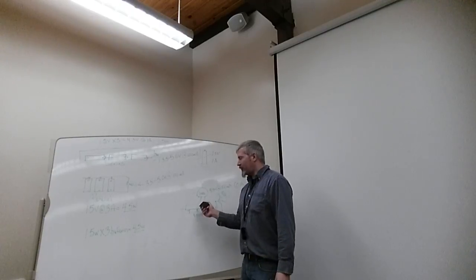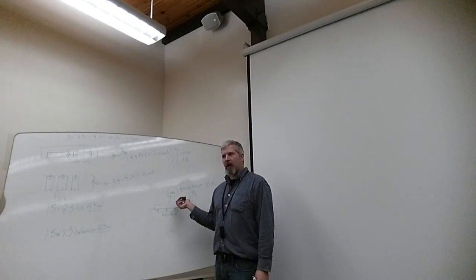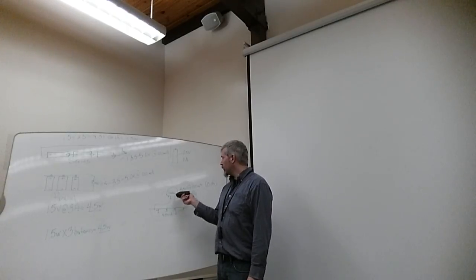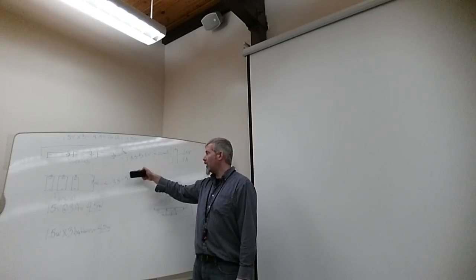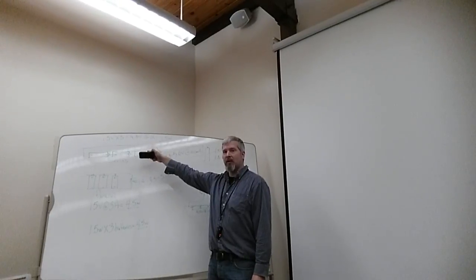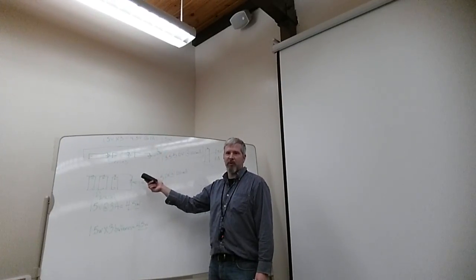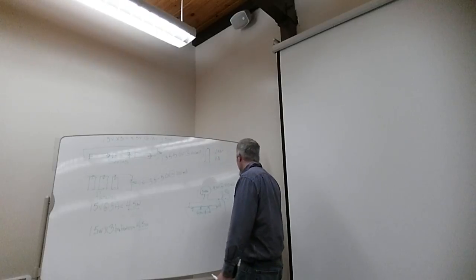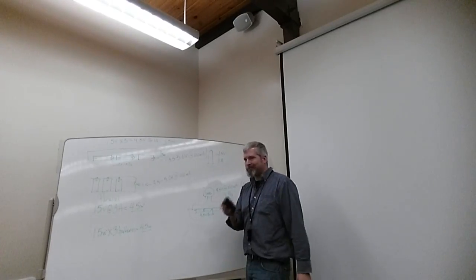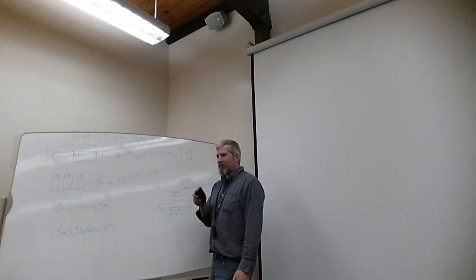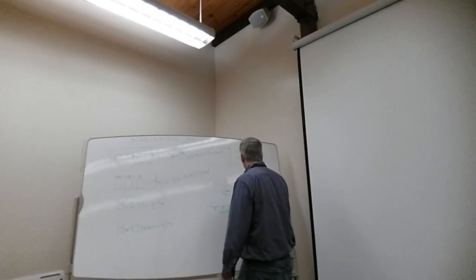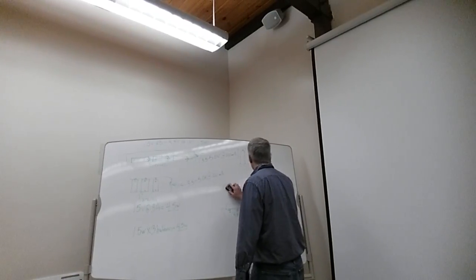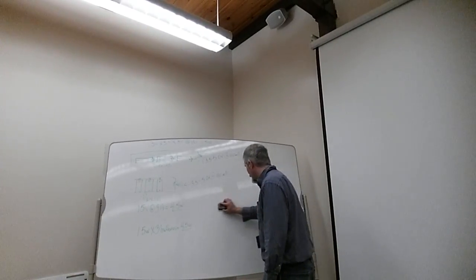Now, like I said, if I put these two in series with each other instead of parallel, what would happen? It wouldn't run, right? Because we would need 3.5 volts plus 3.5 volts, that would be 7 volts. I only have 4.5 volts there, so I'd have to add more batteries to make this thing run. Okay, so let's say you're like, you know what? I really want to use these 3 batteries, but these light bulbs are just killing me. I'm using way too much power for them. So you say, I'm gonna replace these with LEDs. I'm really gonna be fancy here.